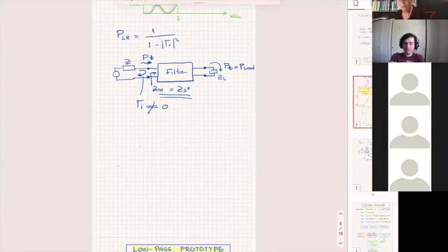And it's a big difference between an hour and 24. So what happens in this particular case is that I say, okay, what are the conditions for highest possible power transfer? Conjugate matching, and that's what I will do. Who cares about perfect match and 0 reflection coefficient if the power that I get is not the maximum that I could? See how I'm thinking? This is how we are thinking about that.